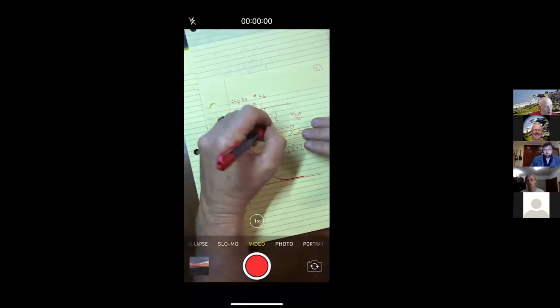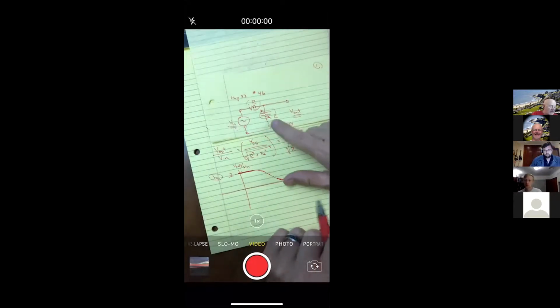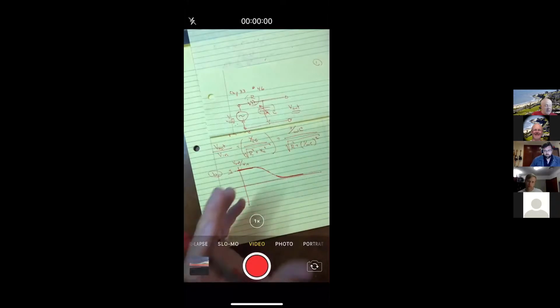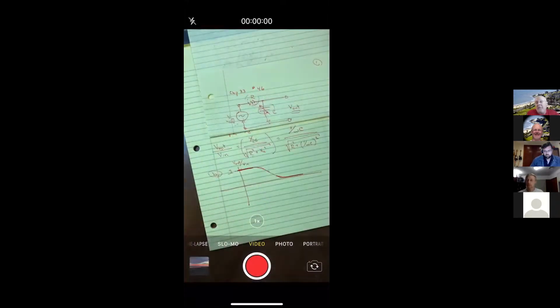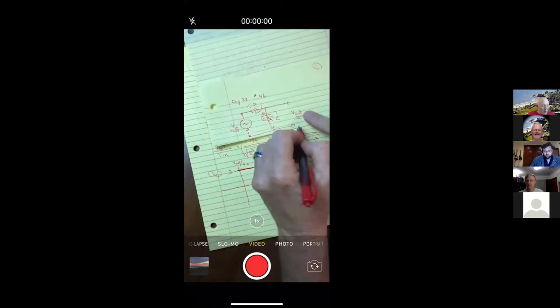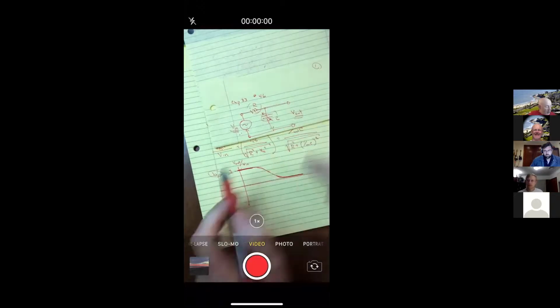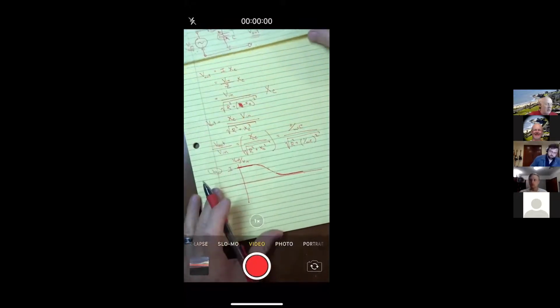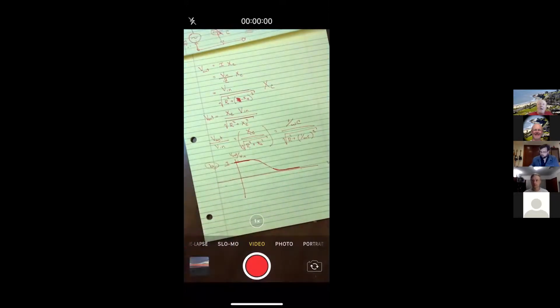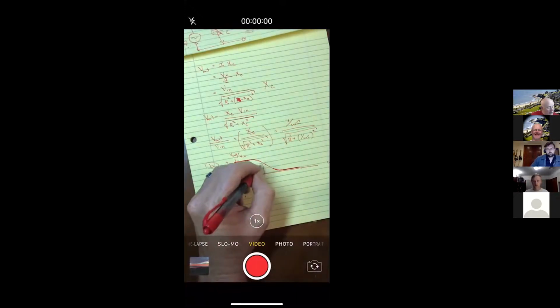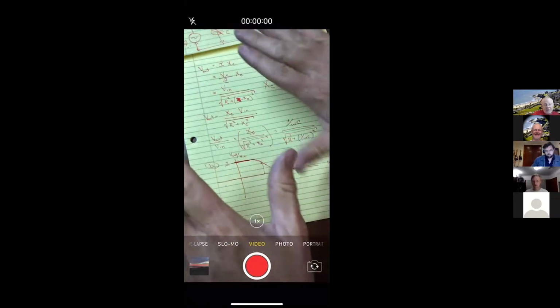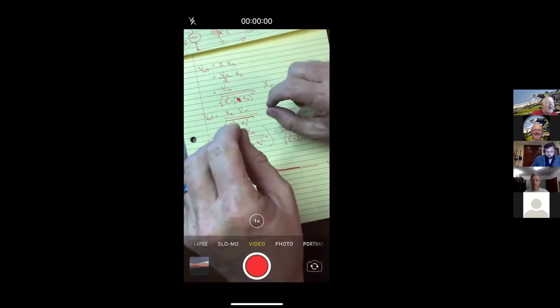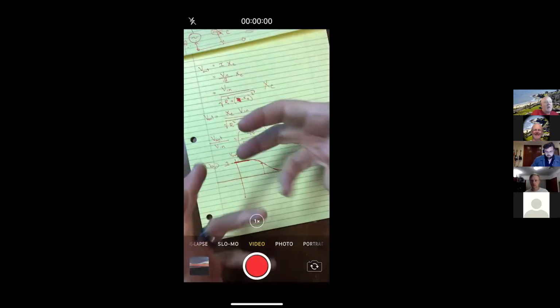Now, to make it adjustable, you usually put in an adjustable capacitor here, so that as I change the capacitance, I can get the bass louder than the treble. And so I filter it a little bit. And so what actually then comes out here, which then goes to the speaker, is heavier on the low frequencies than the high frequencies than what was originally produced. And so that's, again, why we would call this a filter. It's a way of saying, I want to filter out the high ones and keep the low ones. Or it may not be a perfect elimination of them all. You may put it somewhere like here and say, well, that will diminish the high ones a little bit more than it diminishes the low ones. And therefore, I have a higher bass sound to my music.